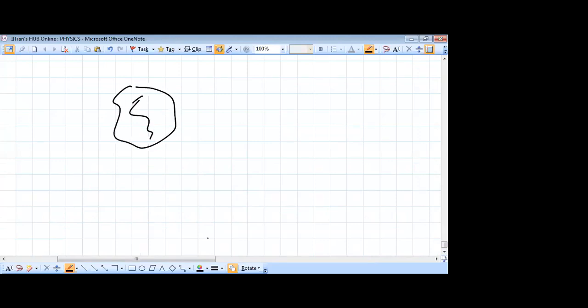So let us say in a rigid body, again, the center of mass is right now here, and is moving with the velocity Vcm. That's our center of mass. And about the center of mass, there's omega. So let us say I'm just arbitrarily finding some point which I'm labeling as O, such that with respect to that point, if I look at the center of mass, then the center of mass seems to be doing circular motion with the same omega about that point. Okay. So I'm not saying just now that that point is the instantaneous axis. Maybe, may not be.